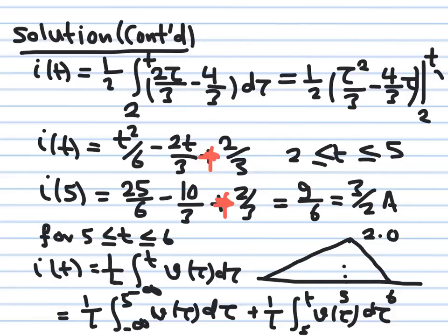So we can now find what will be the initial current for the next step, because we have to integrate between 5 and 6 as well. Remember we have to find also the current between 5 and 6. So we need the initial value at 5. Remember, you are doing an integration when you calculate the current from the voltage, so you need the initial value.